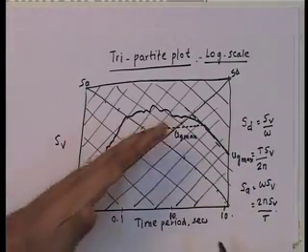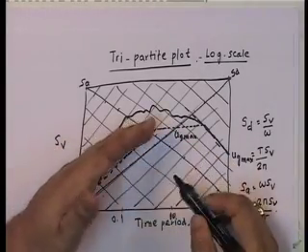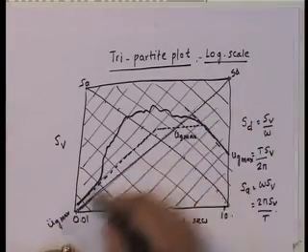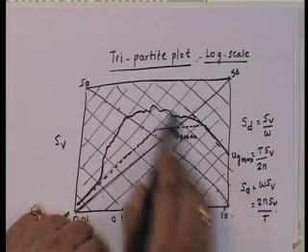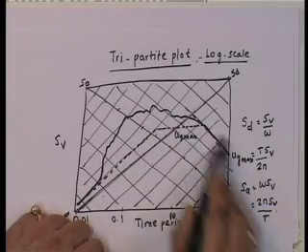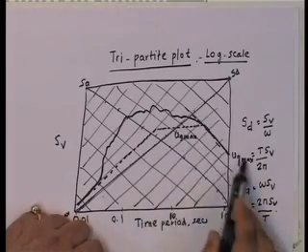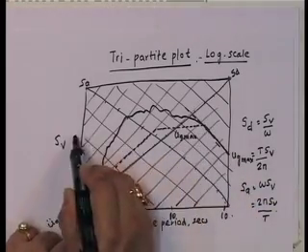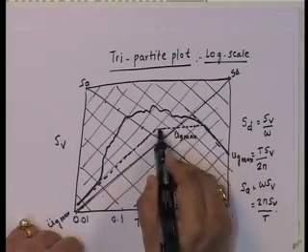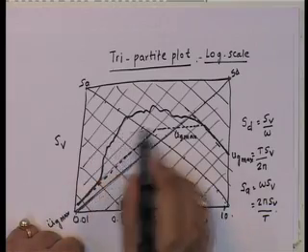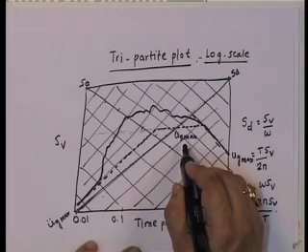So, along this is my plot of my peak ground acceleration, because that is along a constant S A. This is along constant S D. So, this is a plot of the u g max, the peak ground displacement, and S V represents a velocity. So, a constant over this actually represents the peak ground velocity.